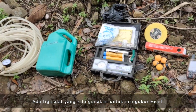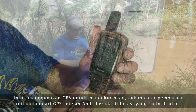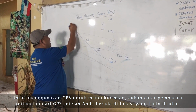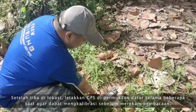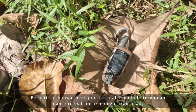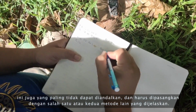There are 3 instruments that we use to help us measure head. First, a GPS. To use the GPS to measure head, simply record the elevation reading from the GPS once you are at the intake site and at the forebay site if you have determined it. Upon arriving at this site, rest the GPS on a flat surface for a few moments to allow it to calibrate before recording the reading. Note that while this is the easiest and fastest method of determining head, it is also the least reliable and should be paired with one or both of the other methods described.